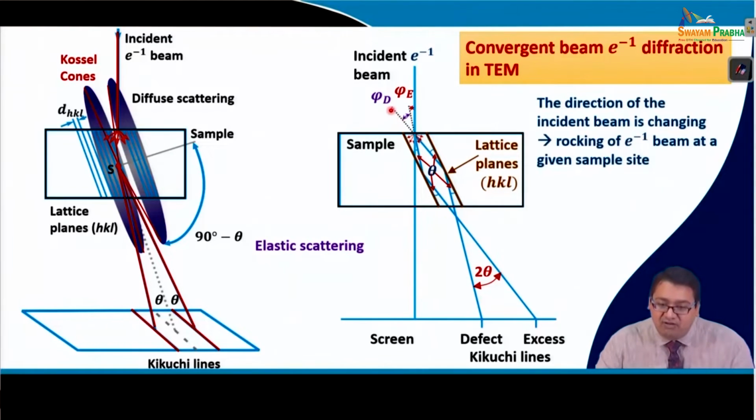So, when it falls on the same HKL plane, it falls like this and scatters inside, that is reinforced scattering following Bragg's law, that is diffraction following a particular theta b for a certain HKL plane. For the same HKL plane in this case, this beam has a lower intensity when it falls here.